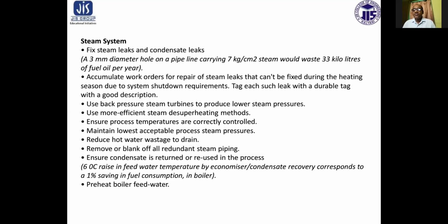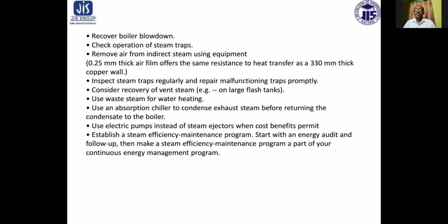Preheat boiler feed water. Recover boiler blowdown. Check operation of steam traps. Remove air from indirect steam using equipment. It is found that a 0.25 millimeter thick air film offers the same resistance to heat transfer as a 330 millimeter thick copper wall.